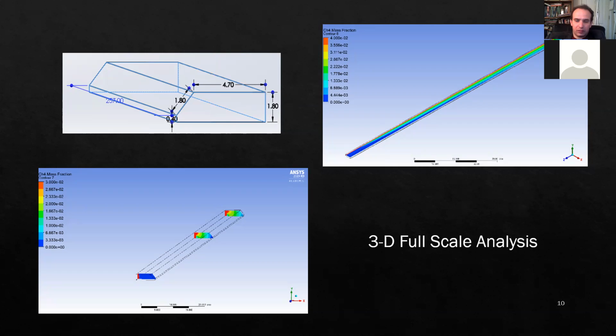I did mess around with, I changed, because we're assuming that the methane being released, like I said, I made an initial assumption that it was pure methane being released as a flux. And those numbers are derived from experimental data in the coal mine. People found concentration rates down here. They're saying that the methane was 100 CFM, which is really just a fraction of the total flow, to take out what the concentration of methane was. So we redistributed that through here, and it may not have actually been 100% methane being released, since the methane content of coal, I think, is believed to be 20 to 60% or something like that.